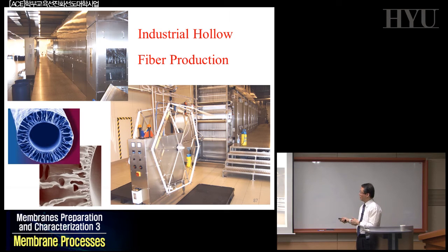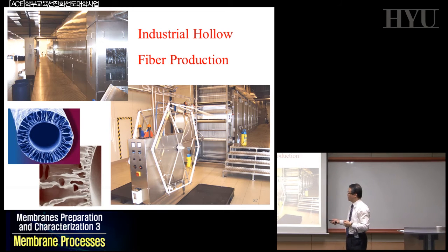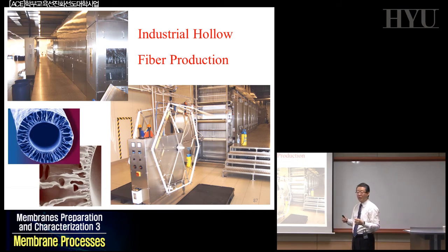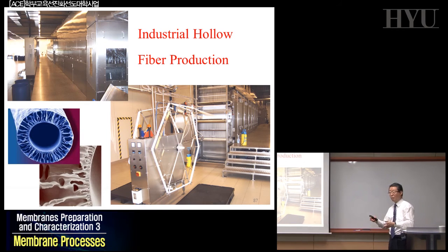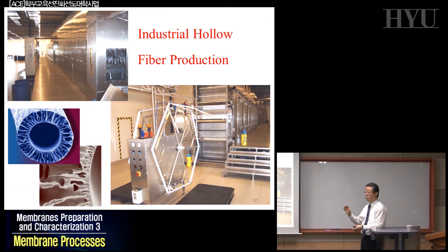But still, even after drying of your polymer membrane, hollow fiber membrane, you may still contain a small amount of residual solvents. The content of residual solvent should be controlled, because if you have residual solvent remaining in your membrane before use, it will affect the final performance of your membranes, because it may be gone during your shipping or transportation process, so your performance might be different. So residual solvent control is very important.